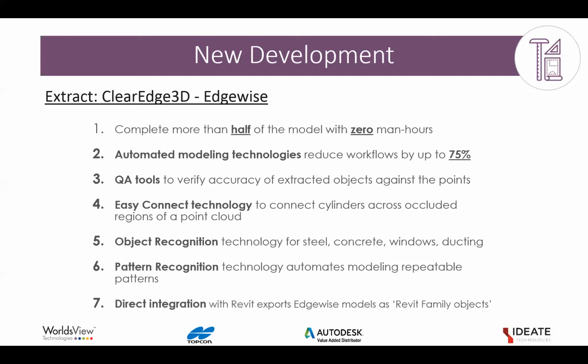And we can use this repetitivity in Edgewise to help it identify and quickly find similar patterns with similar steel frame elements. And this is really something quite interesting. Edgewise can also extract pipelines, which is really helpful for plant and MEP projects. And it can extract ducts to a certain extent.